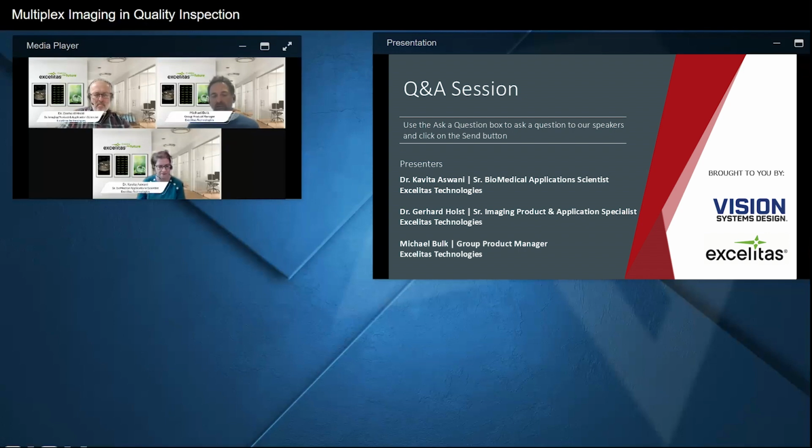VIS, or NIR, then it's probably better to focus on having specific lenses that are designed and optimized for that wave band. So in the UV, for example, you have specific glasses that may only be able to transmit UV wavelengths, and those ones limit the choice that optical designers have when designing a lens. So you may not want to use those type of optics when considering a visible or infrared solution. However, if you are looking for a really broadband solution with many different wavelengths, then you may want to consider one lens that can cover a broader band. So I hope that answers the question.